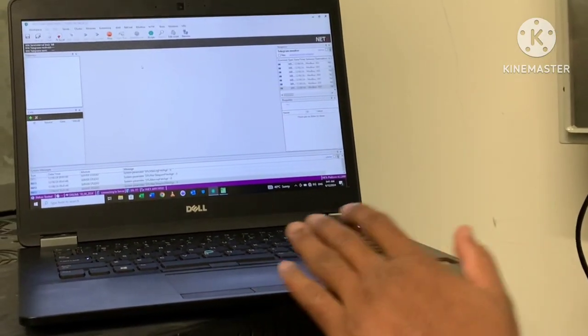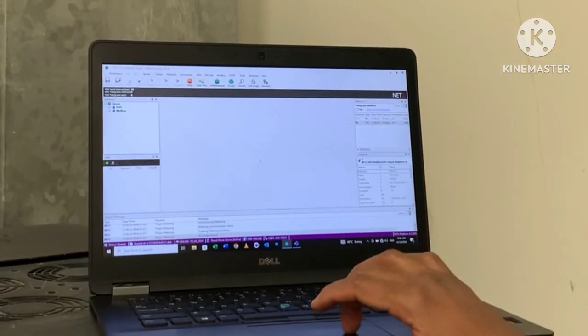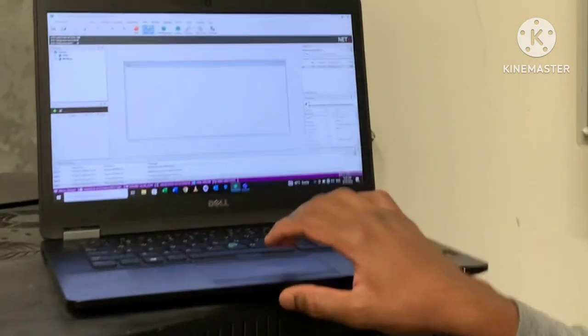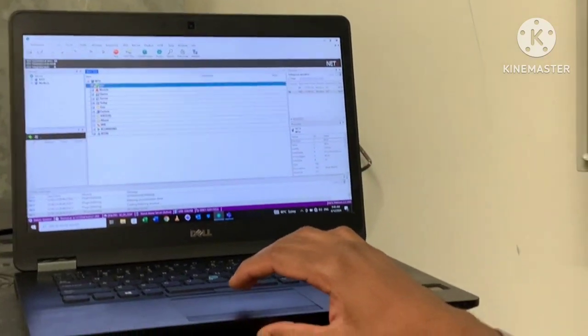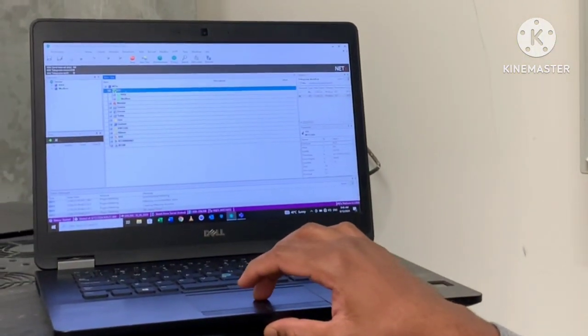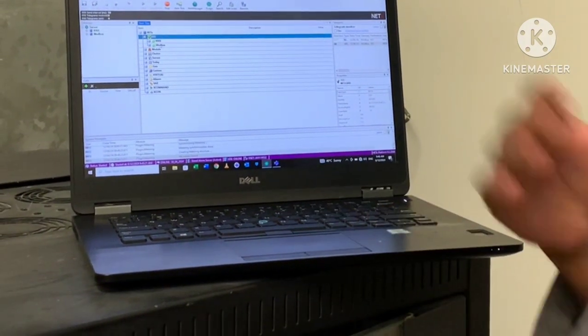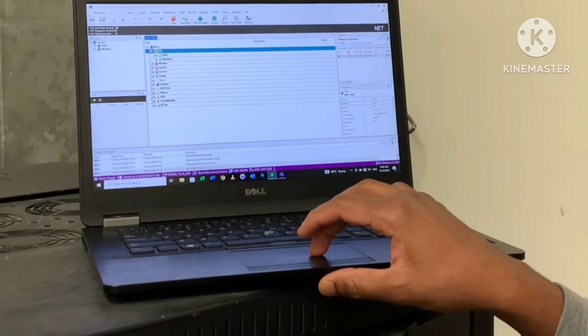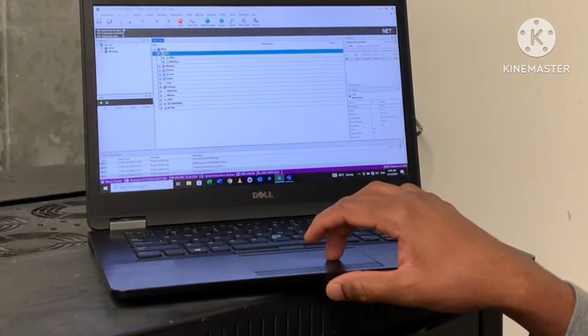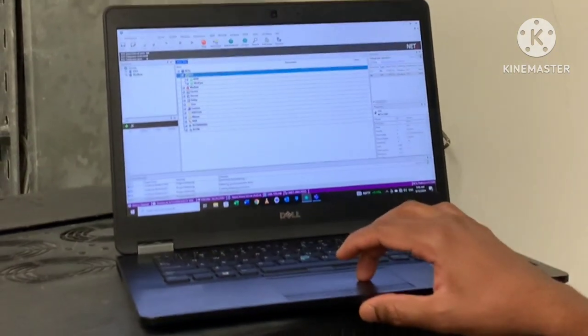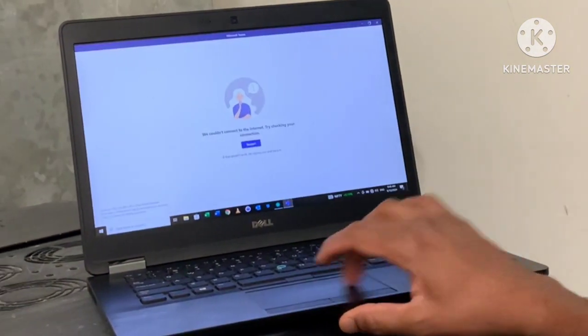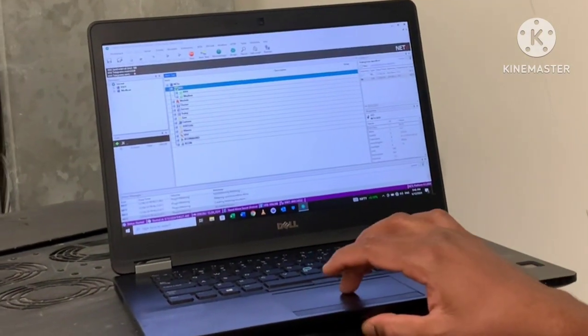It will take some time because I have restarted the system. Okay. So what you have to do, you have to go to item tree and the XIO branch. In the XIO branch, you will find the branches you have linked. Like here, it's showing KNX and Modbus. Okay, if you integrated BACnet also, it will show the BACnet also, SNMP also. Okay, lots of protocols we can include in this system.